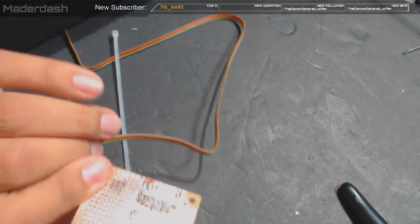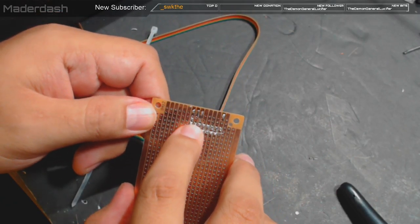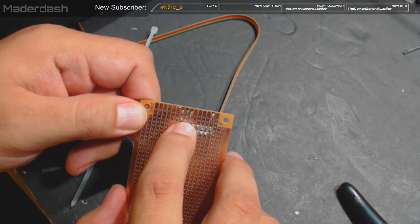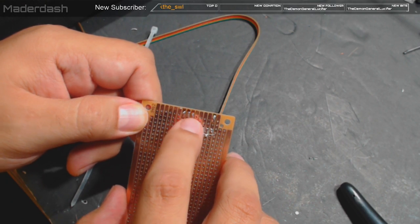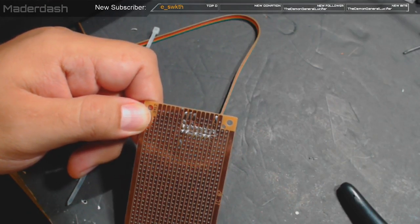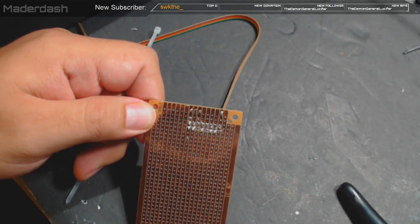Now, in case you were wondering, the reason why I spaced these out by 3, 1, 2, 3, is for future proofing. If it looks like I'm gonna need to put some safety diodes in here, 3 spots ought to be good enough that I could break the trace and put a diode in between these, in case I need to put like a backwards resist diode. That way, if I wire something up backwards later on in the future, and it looks like I'm gonna damage my power supply, then I can put diodes in there just as a precaution,